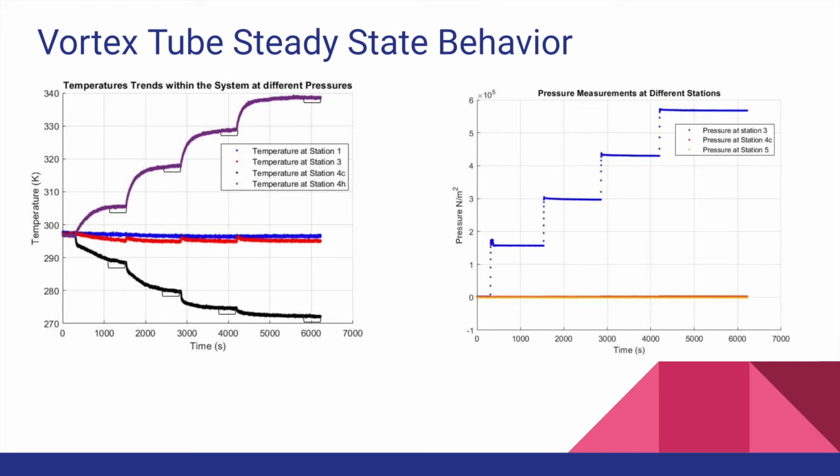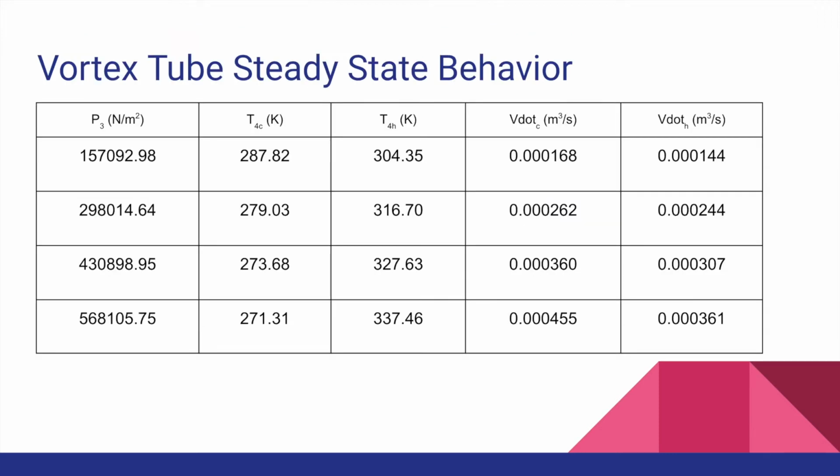After correcting the thermocouple data, we used these plots to identify the steady-state regions denoted by the horizontal brackets on the temperature versus time graph and the horizontal blue regions in the pressure versus time graph. After identifying the regions, we segmented the data and averaged the values to remove noise and get a more accurate answer.